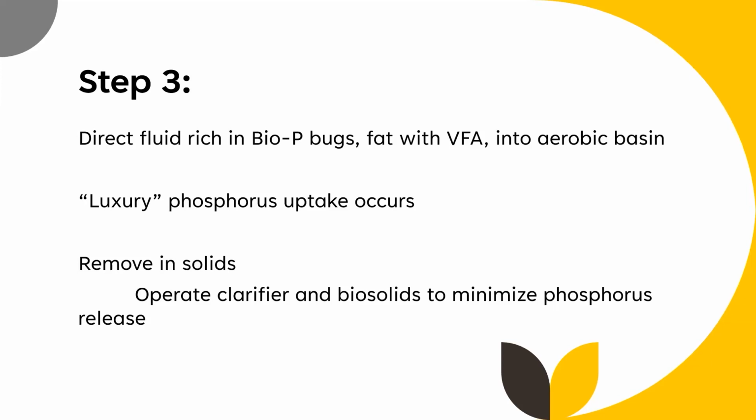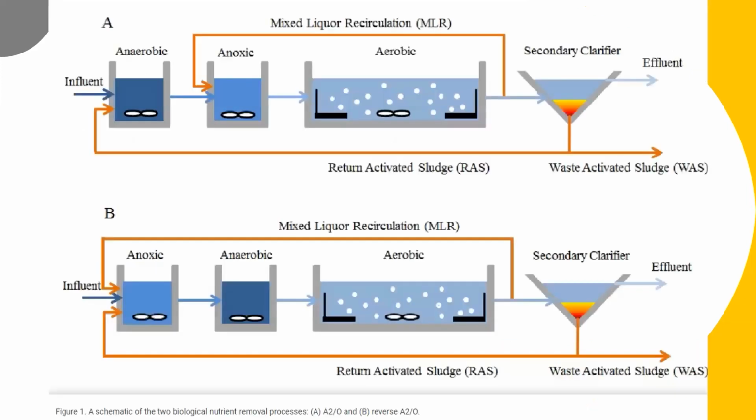It's very important to keep in mind that you can lose phosphorus later on. So you may remove it well in your liquid process and then see it lost in the solids processing of your facility. And we can very much help you in diagnosing what is going on with the flows of phosphorus at your facilities. So going back to this diagram, the keys to phosphorus removal are primarily in that anaerobic zone,